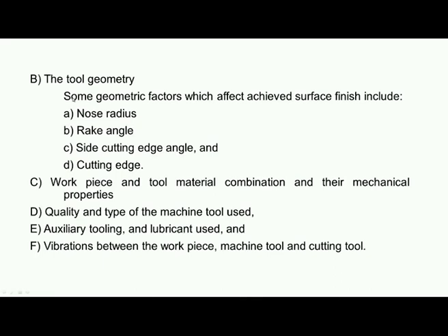And then tool geometry will also affect the surface finish. Some geometric factors which affect the finish are nose radius, and the various angles like rake angle, side cutting edge angle, and cutting edge angle. The cutting tool geometry will definitely affect the surface finish on the workpiece.